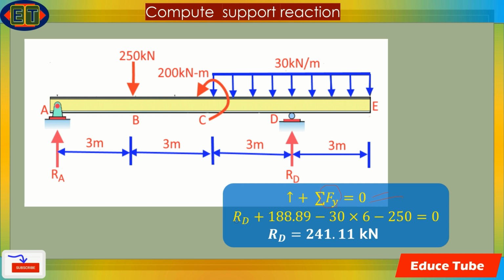So RD vertically up, then 188.89 which we already got in the previous slide, minus 30 times 6 for this load downwards, and then minus 250. So we get RD equal to 241.11 kilonewtons. These are the reactions of the supports.